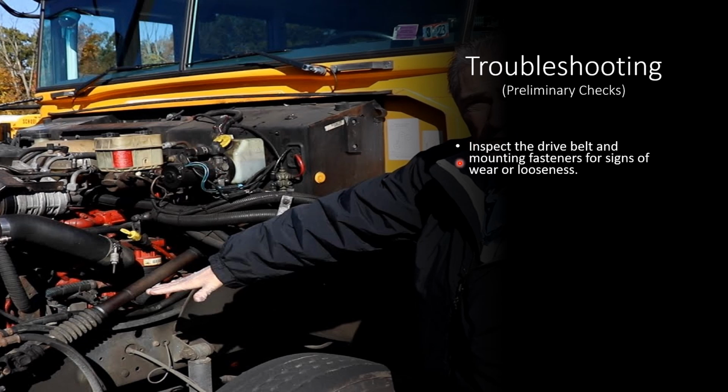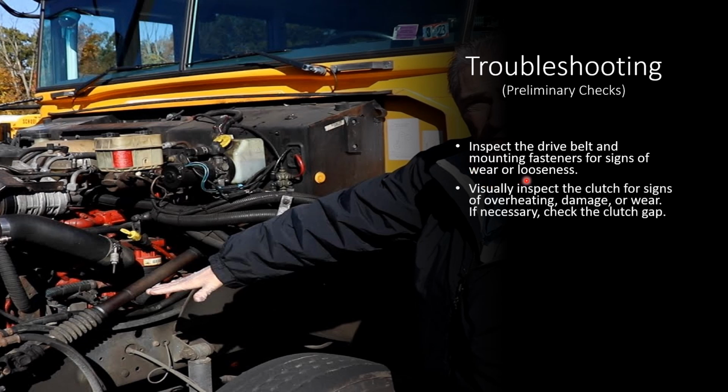Now, these little things, you may think they don't matter, but they do when it comes to the overall operation of the AC system. The next thing I'm going to do is visually inspect the clutch. I'm going to look for signs of overheating or damage or wear. I'm going to turn the clutch, and it should turn freely. There should be no binding. A lot of times if you hear noise in your AC clutch or your AC compressor, it's going to be due to that clutch wearing out, the bearings inside of it wearing out.